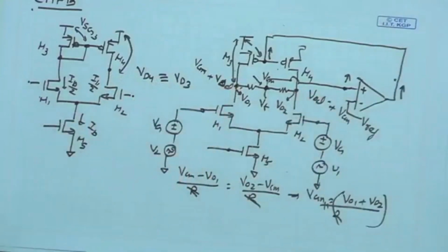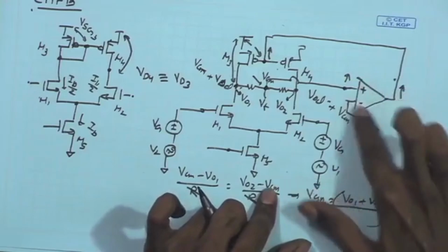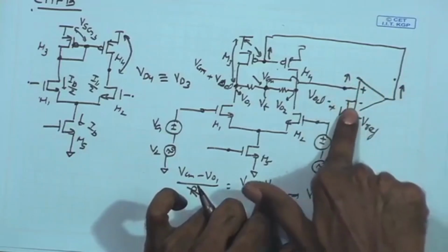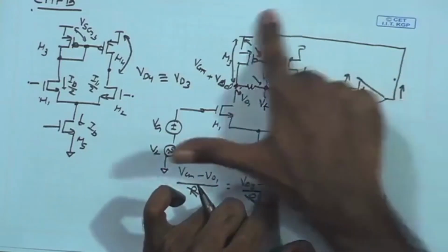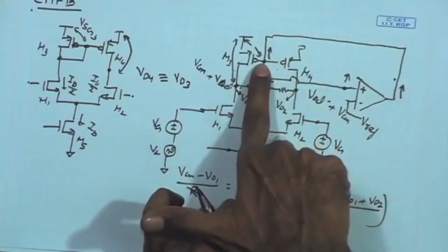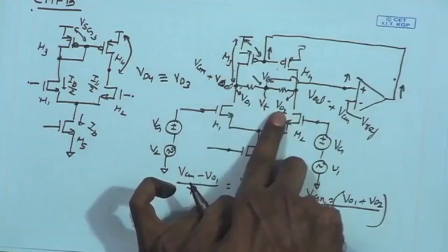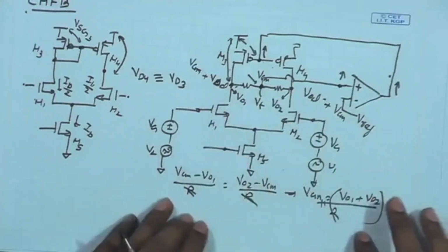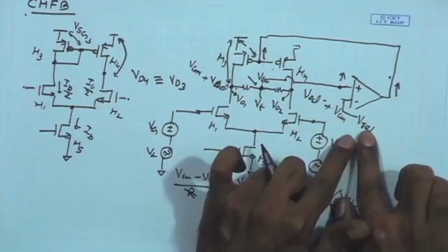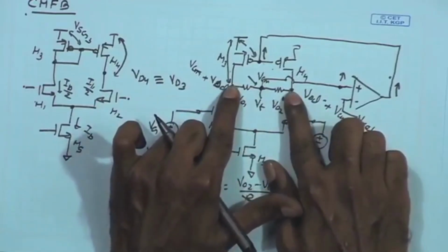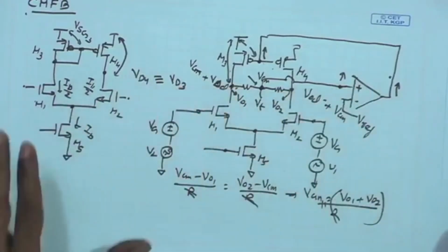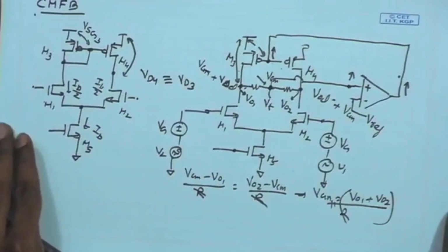So, using this configuration where a differential amplifier with differential input, but a single ended output is controlling the DC bias point at the gate of M3 and M4, which in turn are controlling the DC bias point at the two outputs, we are able to establish a well defined DC bias point Vref at the output nodes. This is the basic mechanism involved in the common mode feedback.